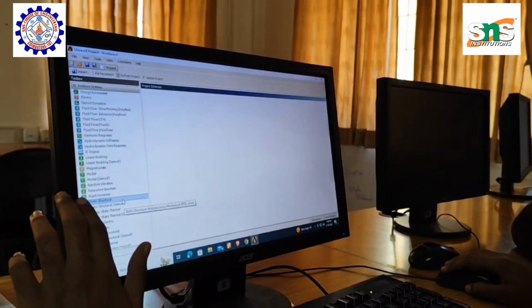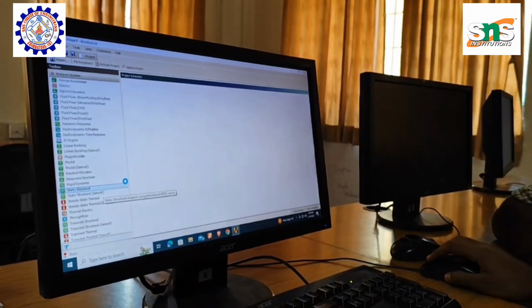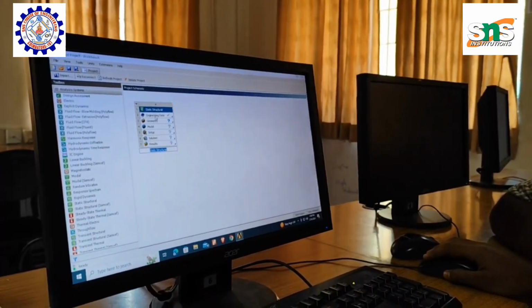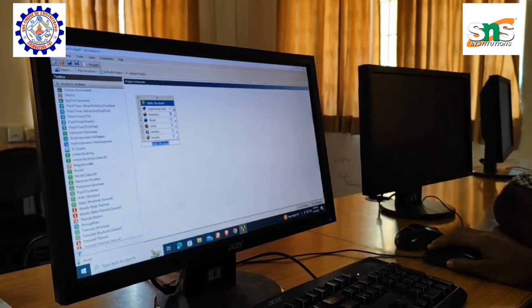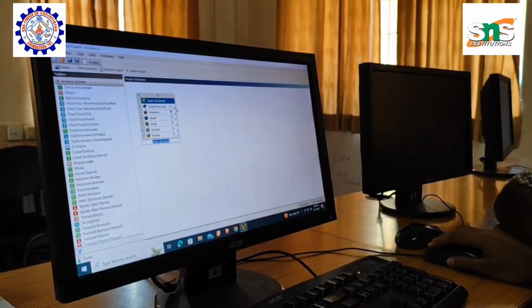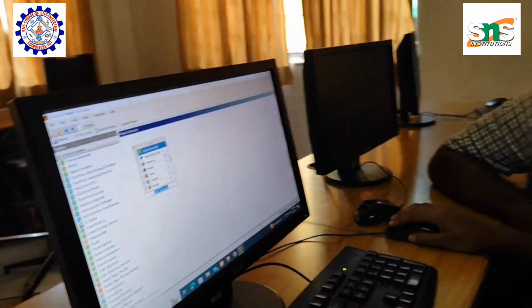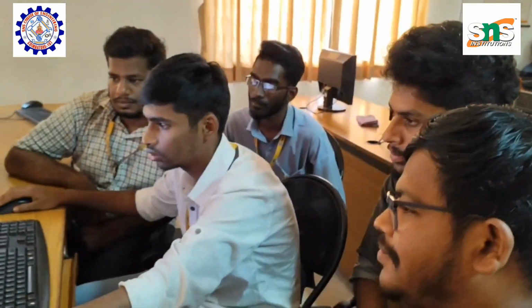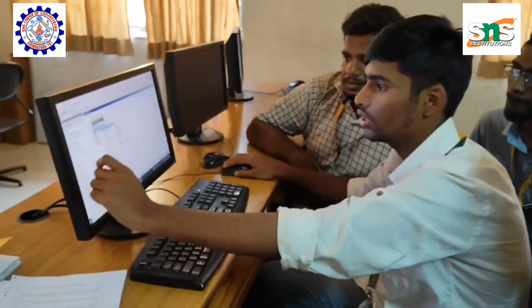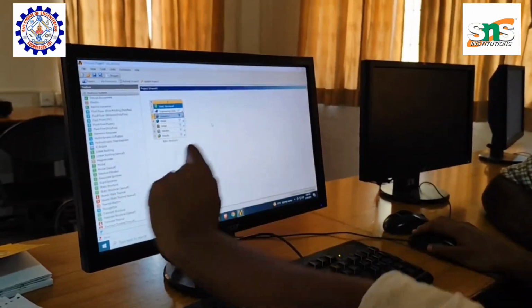I am going to select this one. For everything, there should be a green tick mark. Engineering data, we can keep as the default. Now we are going to select the geometry. We have to import the geometry, so we go to browse.